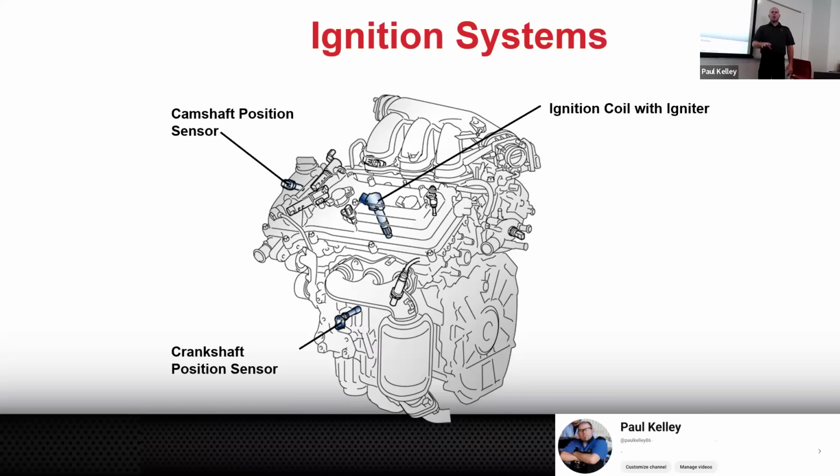And they're like, what the heck is this? Pull it apart, find all the piston rings lined up, re-index the piston rings, put it back together and it fixes it, right? So you can't assume that it's not an engine issue, even with 0 miles, let alone with 10,000, 100,000, 200,000. Anything's possible, right?